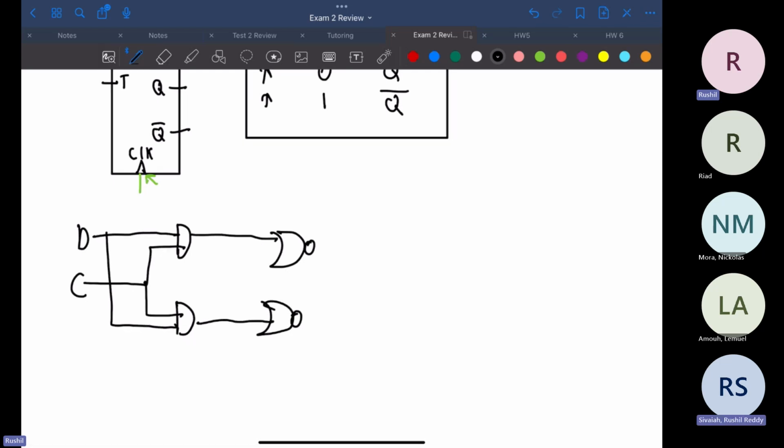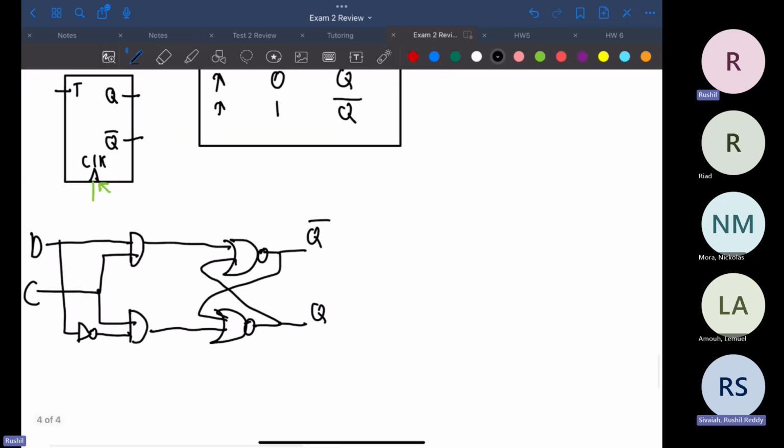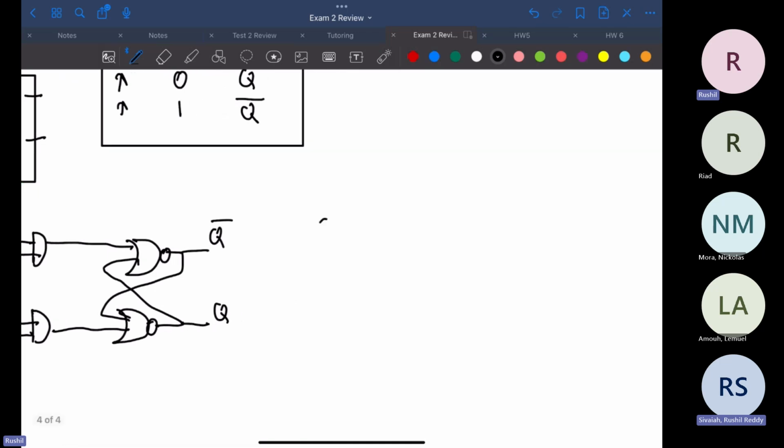What was I doing? Okay, this goes here. This will go here. It's a pretty rough sketch. Yeah, NOR based. Okay, so we have our two inputs of C and D, because a D latch only has a single input. So with that, we have C, D. We can do the 0 at the top, because someone was talking about that earlier. And then we'll have our Q here. So this will hold, this will be a 1, and this will be a 1.